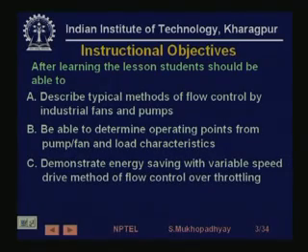depending on how we can vary this operating point. We have to vary this operating point because we need to vary the flow. Now, the flow can be varied by various ways of varying the operating point. Some of these ways may be very simple, but may not be efficient from an energy point of view, while others may involve more complex technology, but possibly would be more energy saving. So, we are going to look at two of the most common techniques and show how their energy characteristics are going to be different.